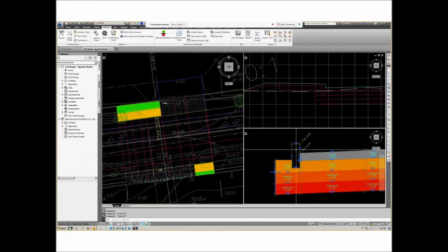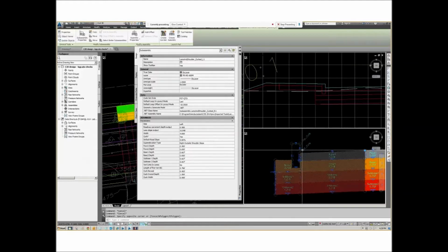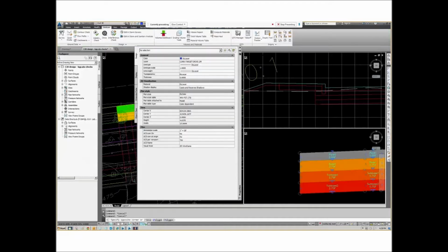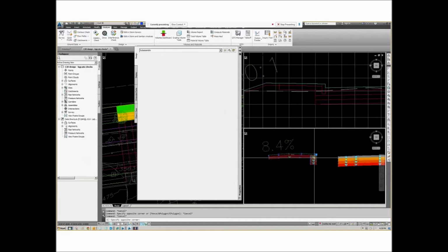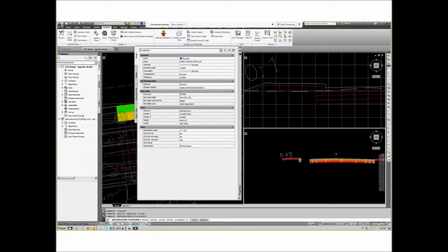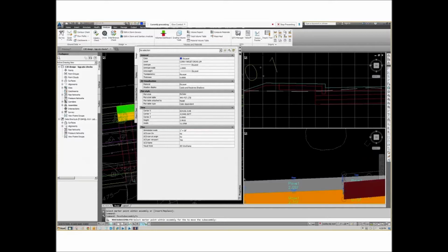When I'm making an assembly for the purposes of using a driveway, I can take this same subassembly, and you can see here a toggle for curb, yes or no. So I can shut off the curb, which terminates that there, and that then allows me to attach my driveway assembly. So here's the driveway subassembly, which I can add to this and move to here.